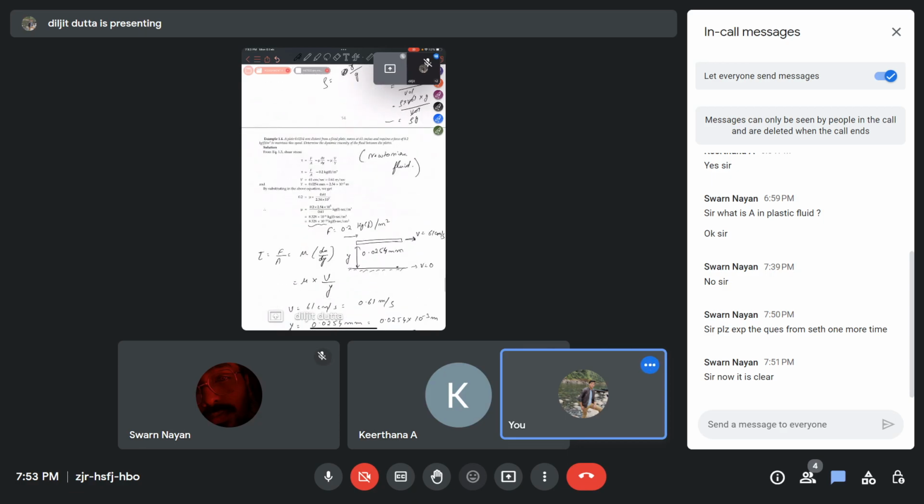And here, tau is the force per unit area. They have given tau here, okay, sorry. Tau is force in kgf per meter square, force per unit area. So mu into du by dy, but we have considered that the slope is linear.